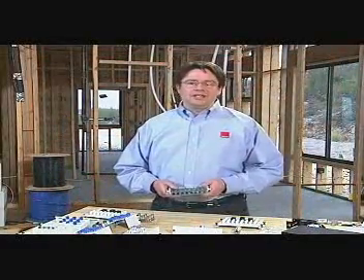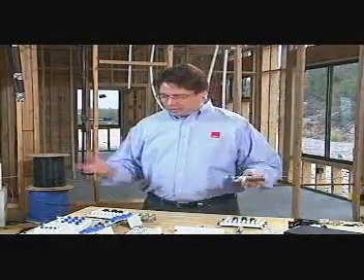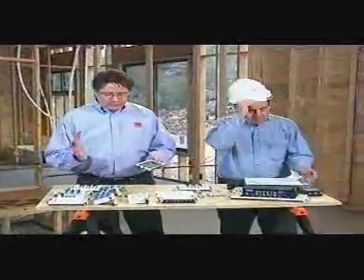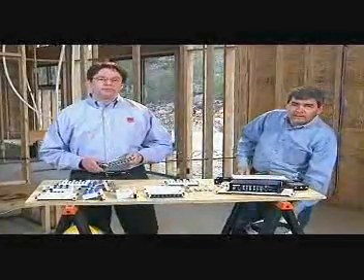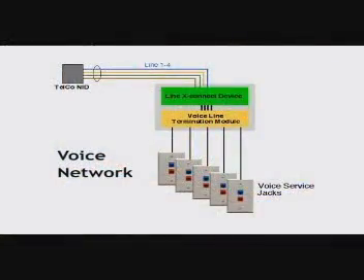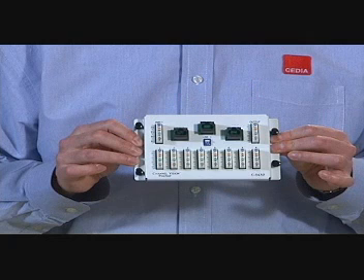Your next step is to design each network and determine the distribution center components necessary to support them. We'll step you through each of the networks, starting with the voice network. Now, the voice network simply needs to distribute at least 4 incoming voice lines to the various voice service modular jacks throughout the home. Each manufacturer of structured cabling products will have some type of voice network distribution module with